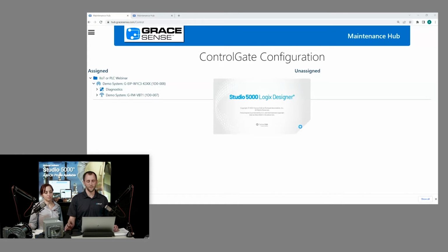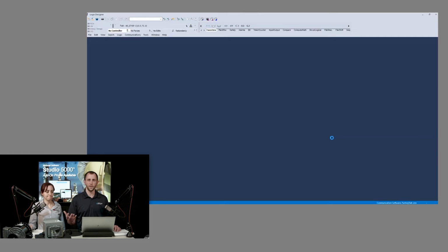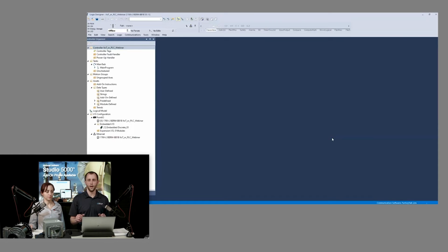That's very fast. There are a lot of unique things we do with that AOP export that I just did. Our memory map is not a static one. So if I add 3 more VBTs to this network, I am going to have a new memory map for that. And there are panel mount nodes so that they can bring in different types of sensors, like 0 to 10 volt sensors. If you wanted to get a CT, or 4 to 20 milliamps for pressure or flow, you can bring all those sensors in, and it makes a unique memory map that we're able to export as an XML file and bring in, so you're not manually mapping all those tags.